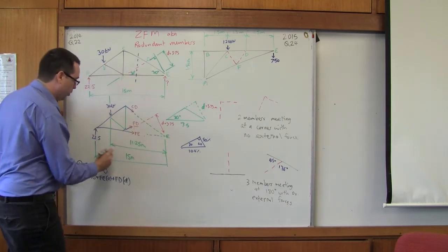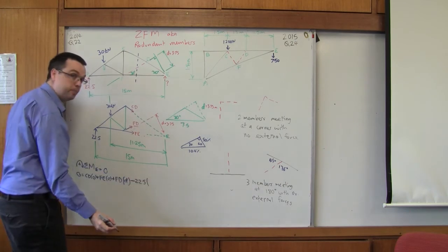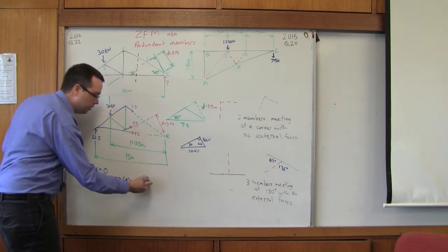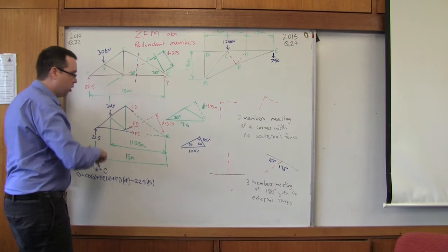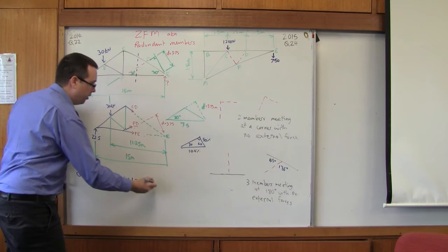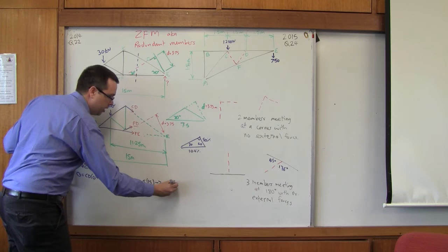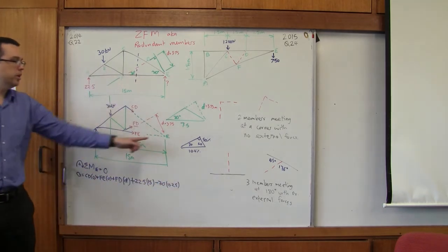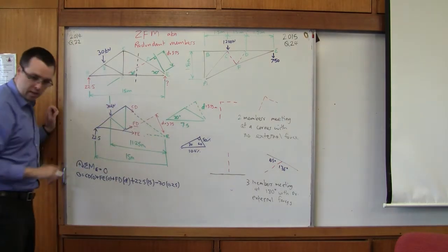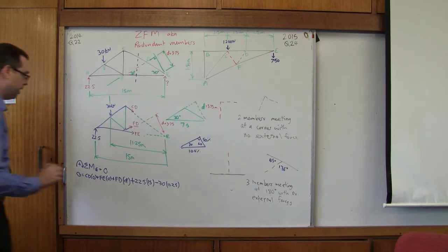And then we've got 2 external forces. We've got 22.5. How far away is it from E? 15. Excellent. And is it clockwise or anti-clockwise? Clockwise. Okay. Positive. And then we have 30, which is 11.25. Is it clockwise or anti-clockwise? Well, it's negative. Anti-clockwise. Okay. So if we type all that in, if you can give me the answer, that would be fantastic.